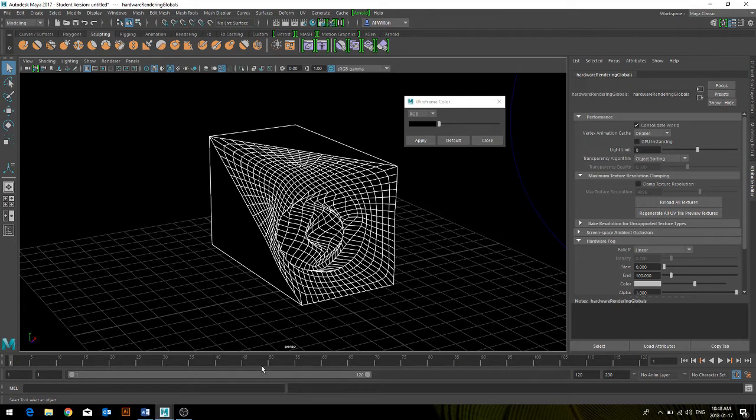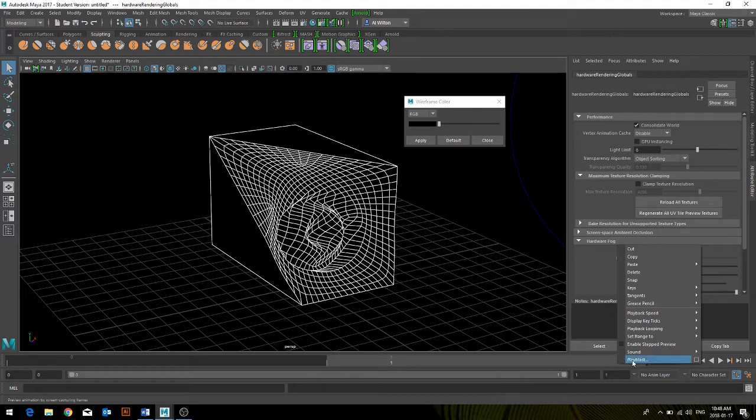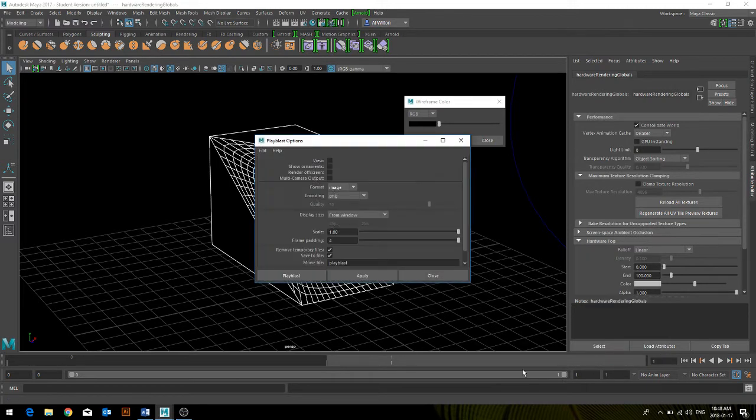And so we'll finally get down to the timeline here that's typically used for animations. And so the 1 to 120 is really the frame count that exists if you are doing an animation. You can export a series of frames which then make up the motion. But for the sake of our use of it, we're only going to be using one frame. So we'll change the settings that you have currently from what it was before to 1 and 1. And then we'll go into Play Blast. So you go up to the timeline here, and you right click, and you go into the Play Blast options.